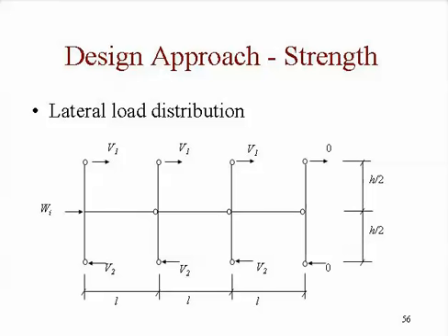So we end up with a column here and a beam connected here through a flexible connection, a semi-rigid connection, but because of the way the loading is on it, this one is not going to be up there at the plastic hinge. It's going to be down in the elastic region because the lateral load is unloading. So I've got a rigid connection here and a plastic hinge over there. And each panel is the same thing, column and one beam, column and one beam. And so what we end up with over here is a pin-ended column with a beam pin connected to it, so it's not going to help in resisting the lateral load.